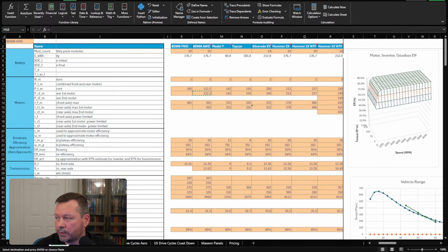So the plan with the actuators is to have them tie into the rear bulkhead structurally, and the front ones to tie into that front bulkhead, and then just support down along the panels for the stationary panel. There's bolts that you can access here. You can take the existing one out, put in a plate, bolt in a bracket. So matching that bolt pattern for sure.